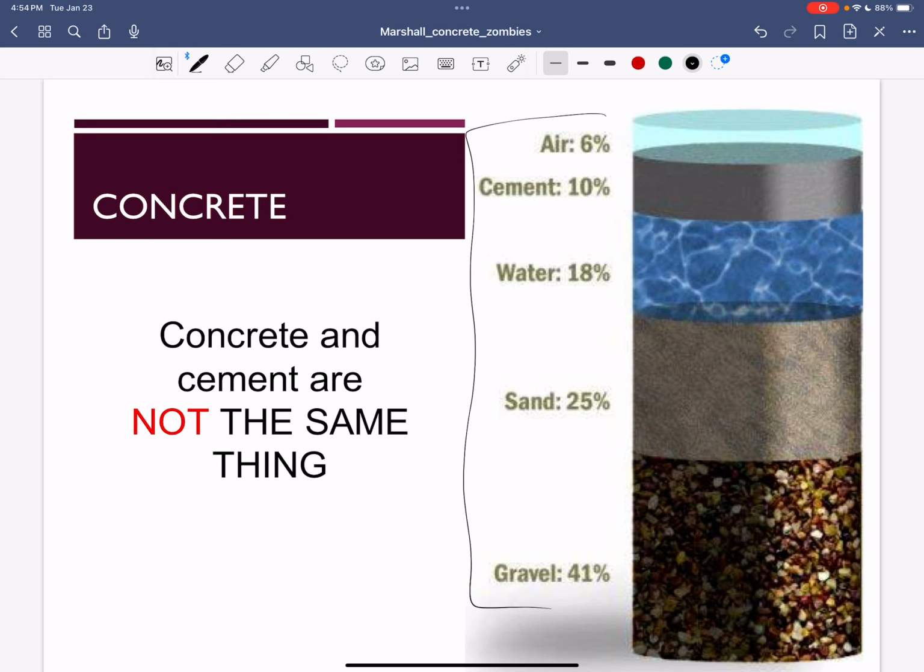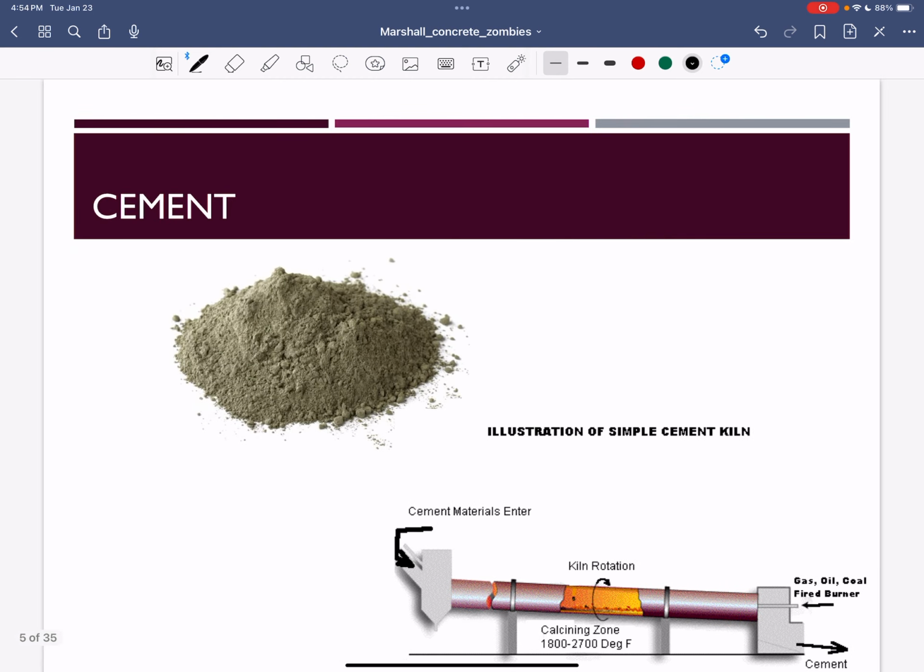We use a chemical admixture to put little air bubbles inside of the concrete, and that helps us resist freezing and thawing. As long as there's space for the water, so let's say there's a little moisture in the pores, as long as I have space so that it doesn't fill up, it won't freeze and crack the concrete. That's a whole other discussion, but it's something you'll see in concretes around here in Minnesota: we'll have around 6% air. So cement.